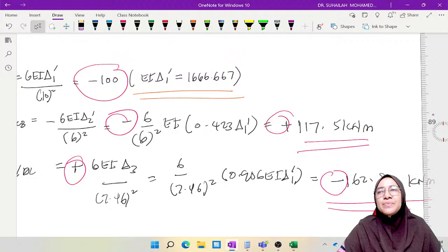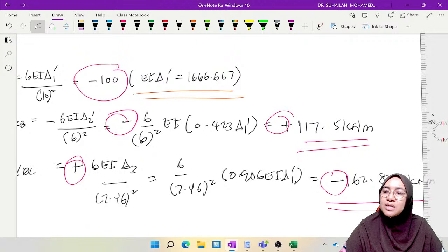If we have actually set the Excel to calculate the end moment from table 1, where in table 1 we calculate FEM due to loading, then in table 2 we just need to change the FEM only. And this is the most complicated part in moment distribution method.